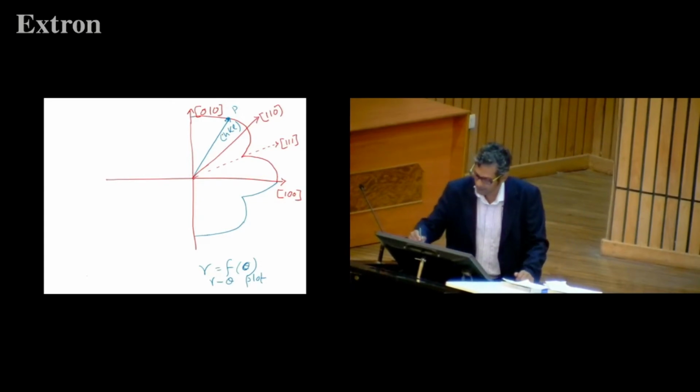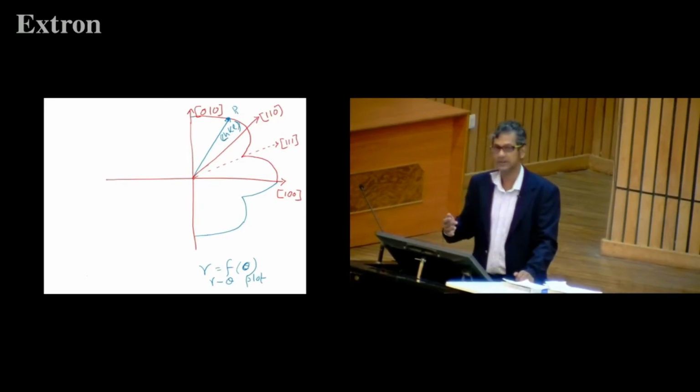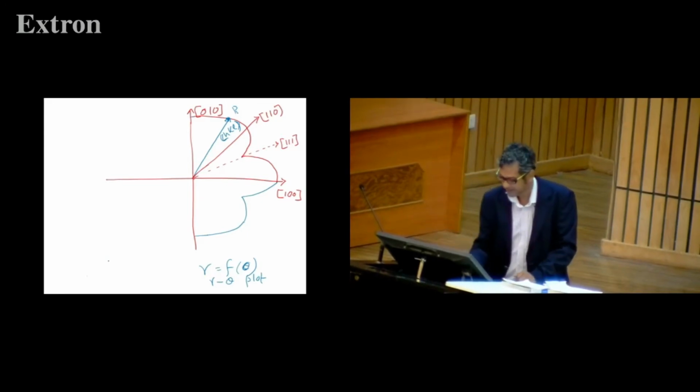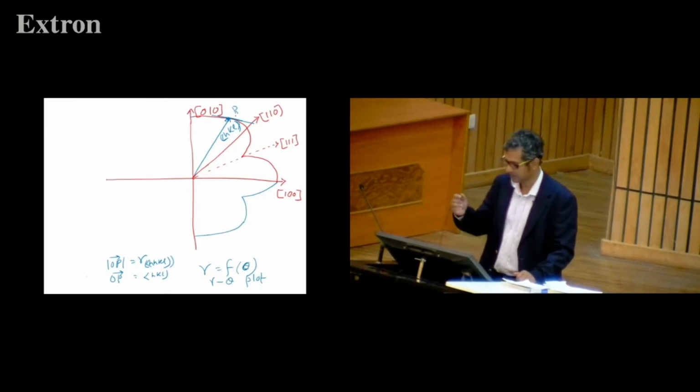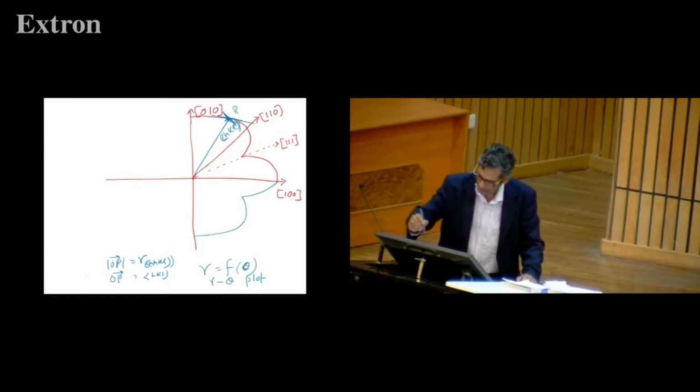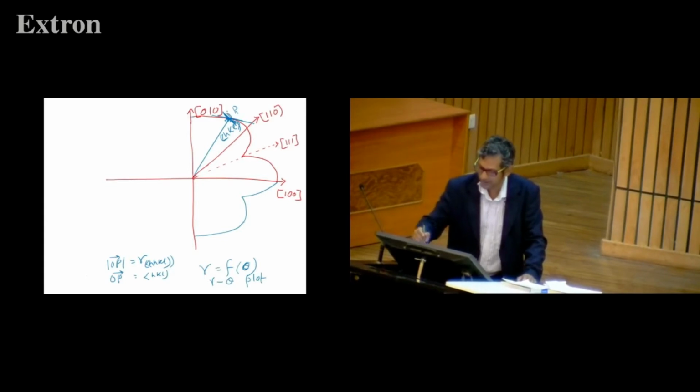Now, if this is the direction like that, the value of the surface energy is basically the magnitude of this vector, that is the value of gamma HKL, and the direction vector is telling you the HKL direction. Then at this point if you take a 90-degree cut, or basically take a normal, this normal can then be used to create a shape inside it.